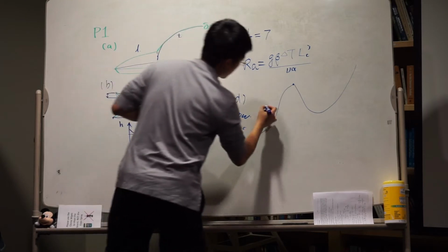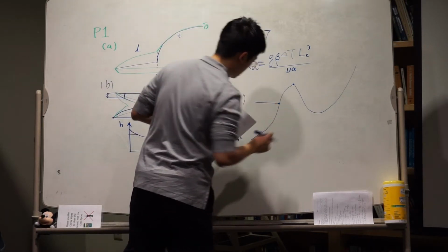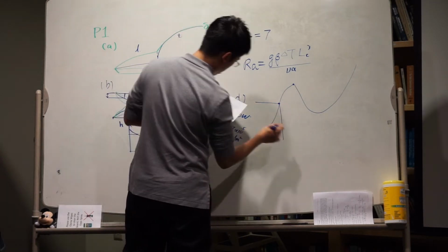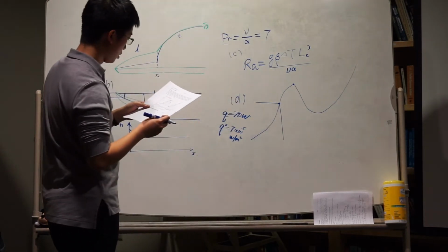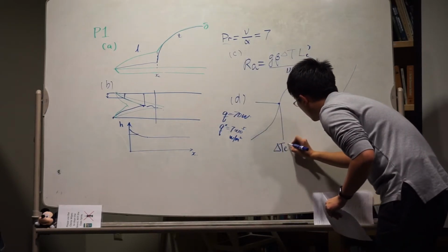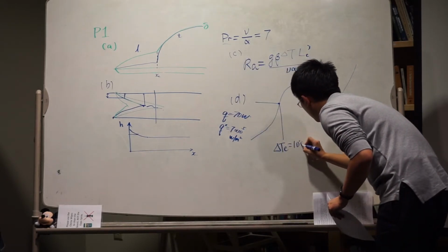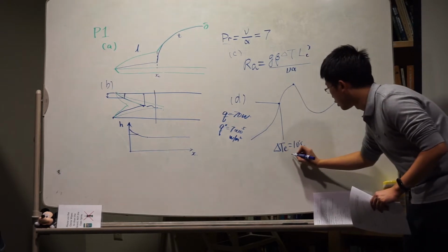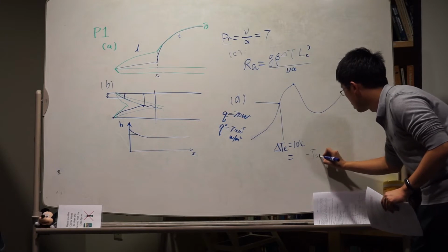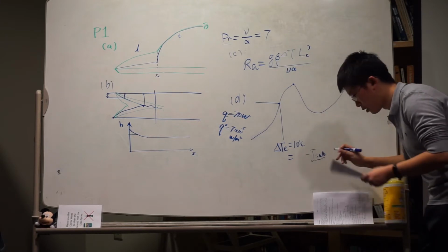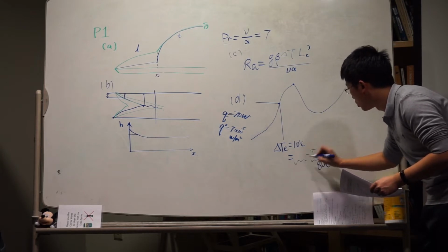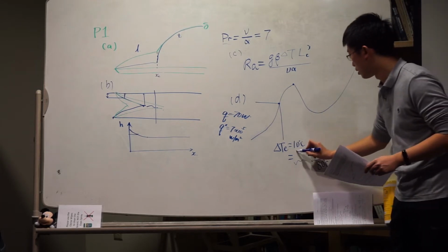We look at the curve, we find, okay, it must be this point. And then for the corresponding temperature, we can read that the excess temperature is 10. And we know the saturation temperature is 80. And we'll know the actual surface temperature is 90.